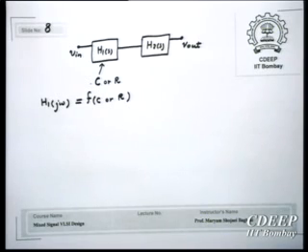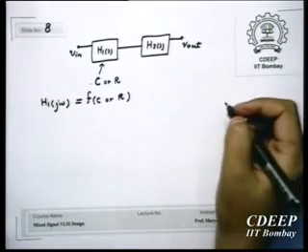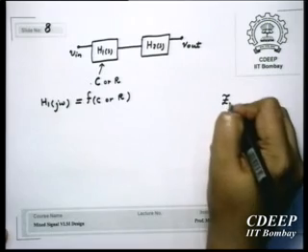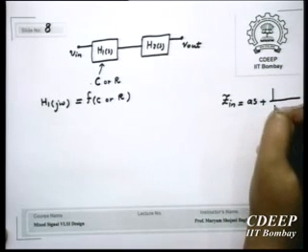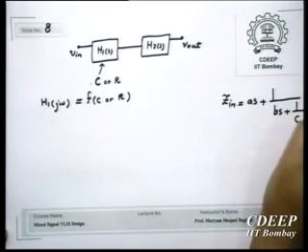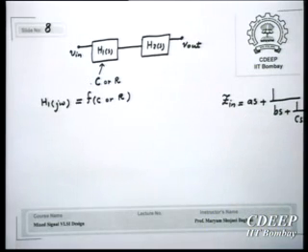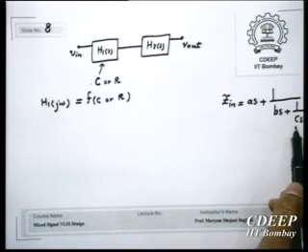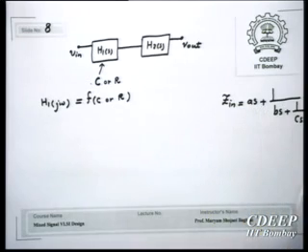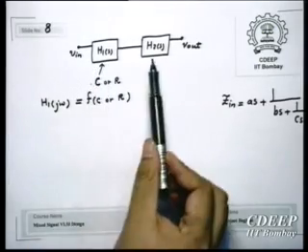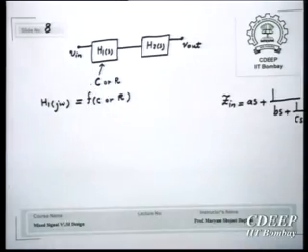In the case of ladder, if we change a component value, it will change many coefficients because all are integrated together. Because if you remember, to realize Z in, it was, for example, As, then 1 upon Bs, plus again 1 upon Cs, and so on. So if one of them changes, the effect will get translated here, again it will come here, and so on. Therefore, many coefficients will change. But in the cascade, at least you can make them a little isolated.